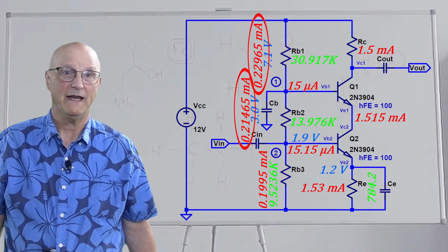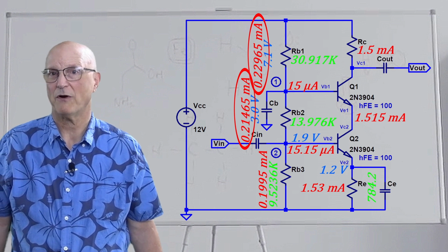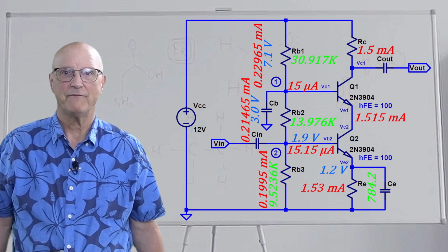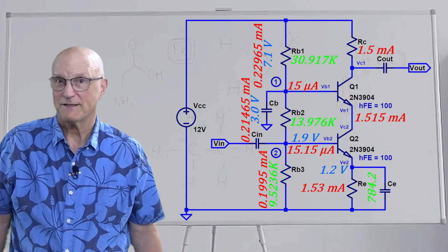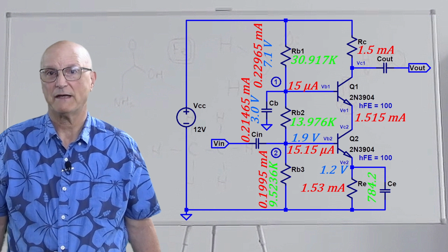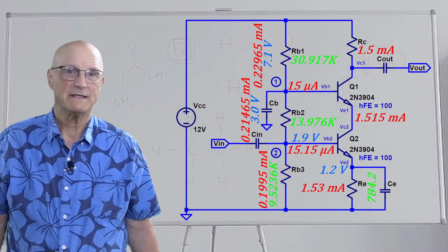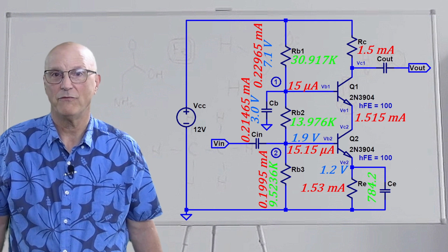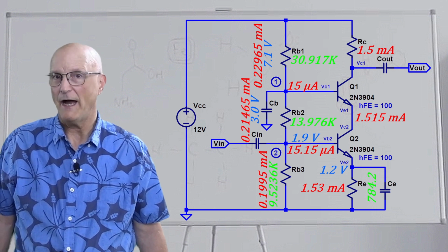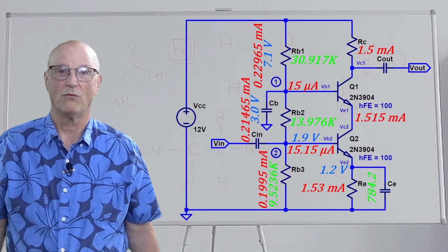As a result, we need a lower resistor value for Rb1 to maintain the required voltage drop across it with the higher current through it. The lower calculated value of Rb1 acts like a larger value than it actually is when viewed from the perspective of the voltage across it and the current through Rb2. This is why we had to calculate the value of Rb1 from its voltage drop and current flowing through it, and not by subtracting the value of Rb2 from our calculated value of R1.